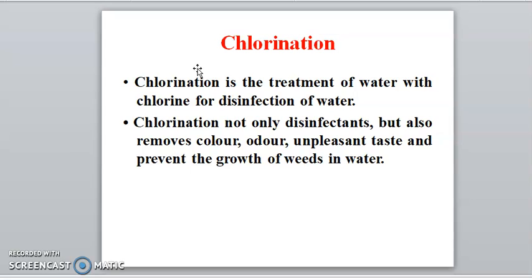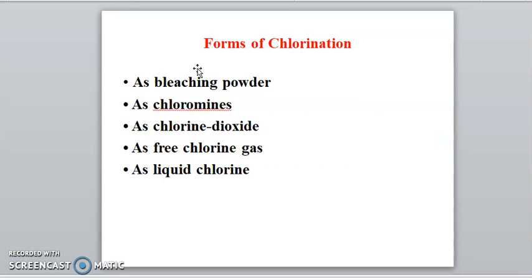Chlorination is the treatment of water with chlorine for disinfection. Chlorination not only disinfects but also removes color, odor, unpleasant taste and prevents the growth of weeds in water. Forms of chlorine: bleaching powder, chloramines, chlorine dioxide, free chlorine gas and liquid chlorine.